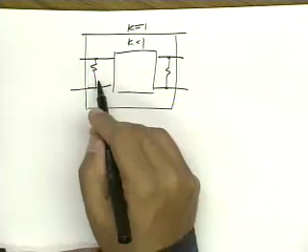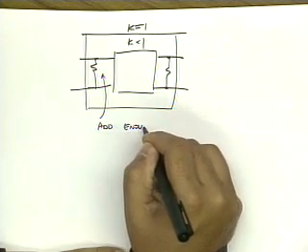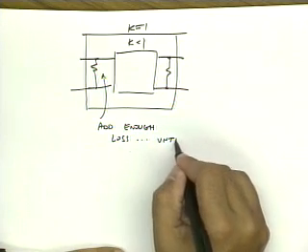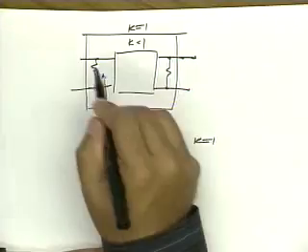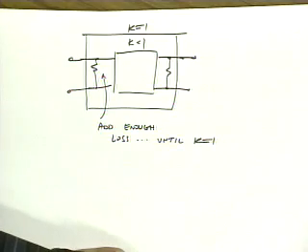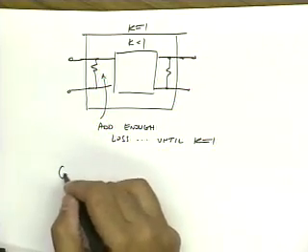So we add enough loss until K is equal to 1. And then we actually have something from the external two-port here that looks unconditionally stable. And so then the expression GTmax applies.